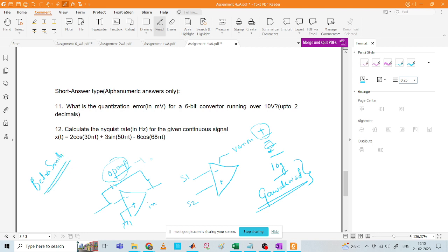Just study about operational amplifiers, but I can give you the very basics. Operational amplifiers are used so that you can perform any kind of operation on analog signals. That is the reason it is used for A to D converters, because it converts an analog signal to a digital signal. Though the op-amp operates on the analog signal and can give out an analog signal, it can also give out a digital signal by making the op-amp work as a comparator.